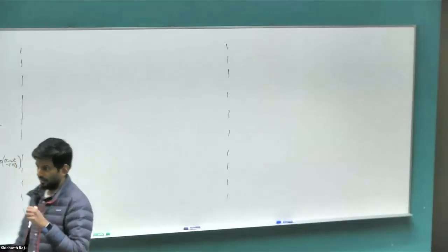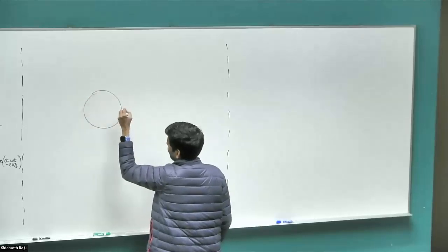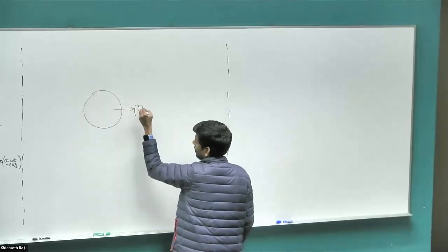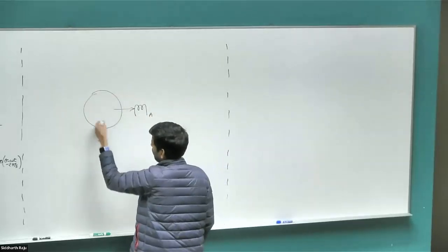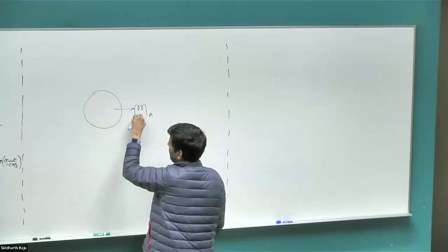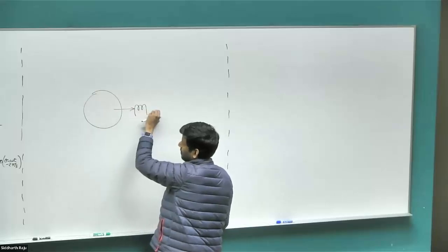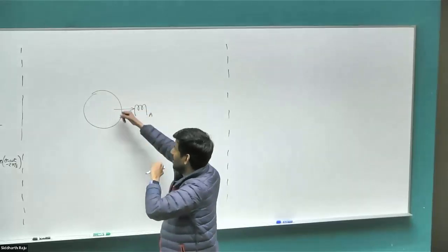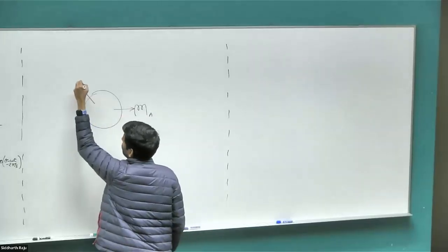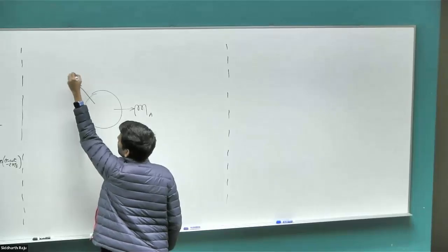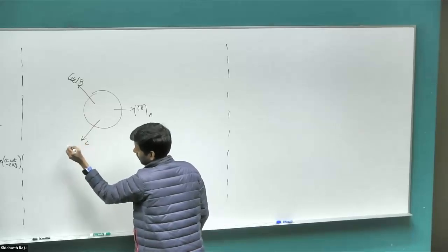Okay, so going forward, I'm not going to be drawing all of those windings. Instead, I'm just going to represent them as a coil. When I draw this diagram, this means that there is a sinusoidally distributed winding representing this one. The peak density of that winding is here, but the peak magnetic field of that winding is along this direction. So I'm drawing the solenoid diagram exactly where the magnetic field of that particular phase would be at its peak. And then I have the peak of B phase here, and then the peak of C phase here.